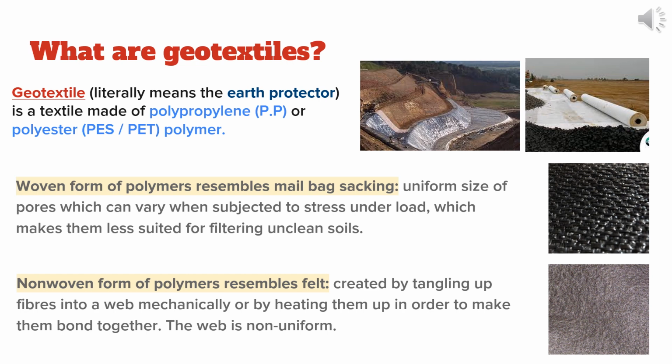They are manufactured in large sheets that can be easily transported to construction sites. Geotextiles embedded in the compacted sand and gravel act as isolator and reduce the impact of large ground deformations due to fault rupture. Geotextile is a planar, permeable, polymeric, synthetic or natural textile material, which may be woven or non-woven, and can be used in contact with soil or rock or any other geotechnical material in civil engineering applications.